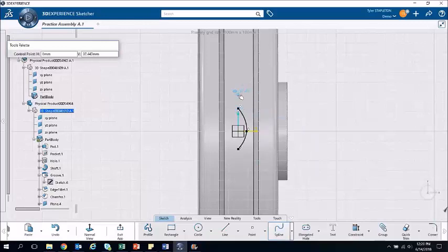Now as I'm doing this, notice if I line it up with the axes, I get a little icon there and a blue dotted line showing that it's going to be constrained to always be in line with that arrow. And these points that I created have a little circle showing that that constraint exists. Now as I bring this down and line it up with that point, you notice that circle icon becomes filled in. That's showing that they're coincident, and if I leave the point there, it's going to be fixed to that point.